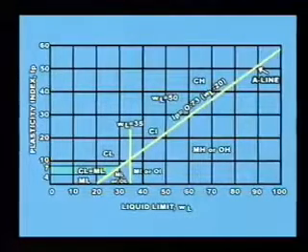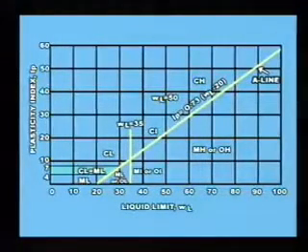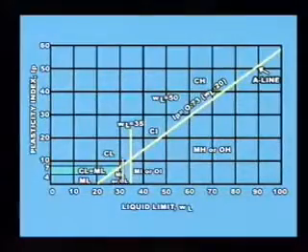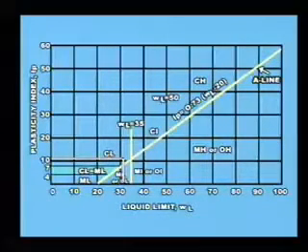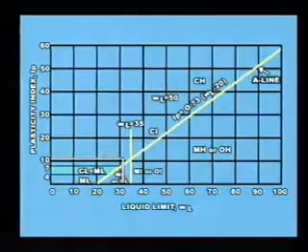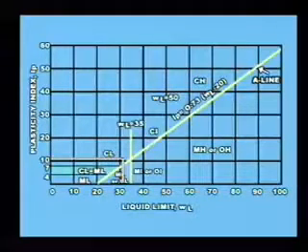Finally, to classify the soil, we refer to the plasticity chart as per IS code 1498. In this case, the liquid limit is 31.5 and plasticity index is 10.34. Thus, the soil is of CL type, that is clay with low compressibility.